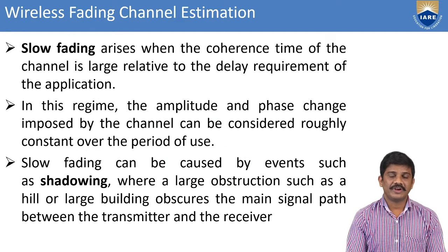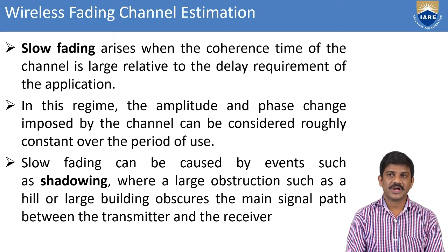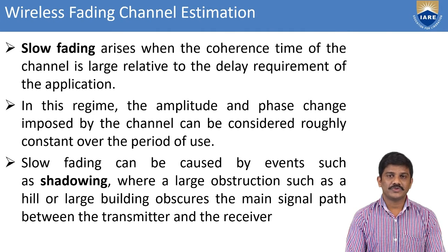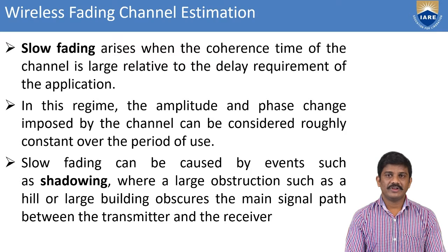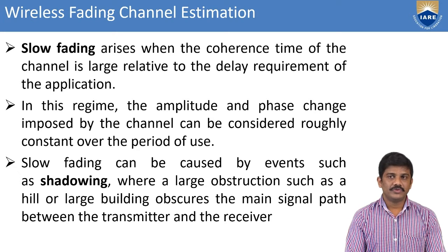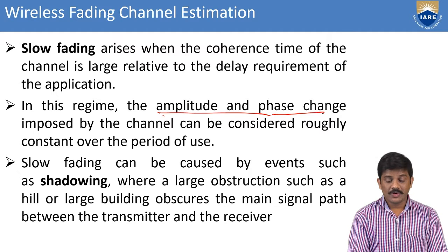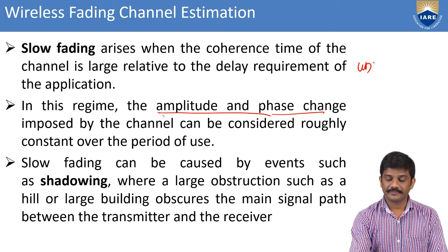Okay, coming to slow fading, it arises when the coherence time of the channel is large relative to the delay requirement of the application. Any amplitude or phase change imposed by the channel is considered roughly constant over the period of use. Okay, here we can consider the amplitude and phase changes. Okay, we are having the unbiased function also.